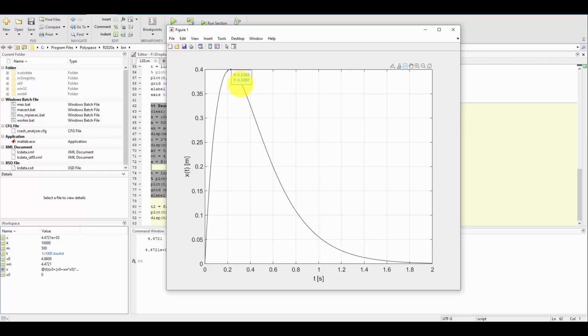And then what happens, it goes to its maximum value, and then its x value is decreasing as it comes back towards equilibrium. And what we see is it's asymptotically approaching 0. There's no overshoot. It is slowly going back to its equilibrium point at 0. And that's a hallmark of this being critically damped, or really it not being underdamped. If this were an overdamped system, then we would see that it would more slowly asymptotically get towards 0, but that's why we want it to be critically damped, so that we would return as quickly as possible without having overshoot.